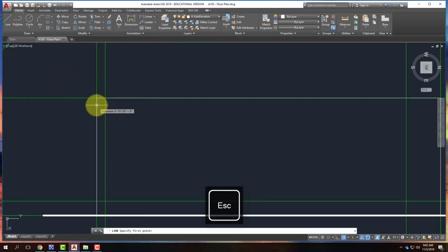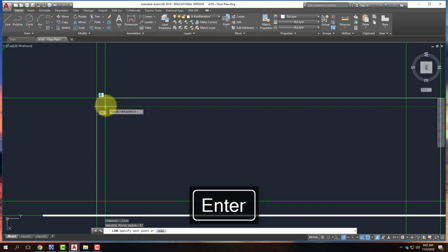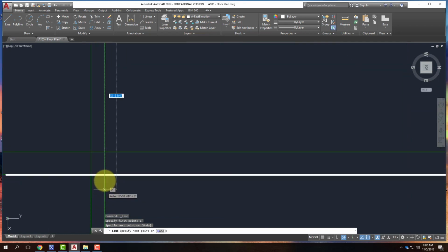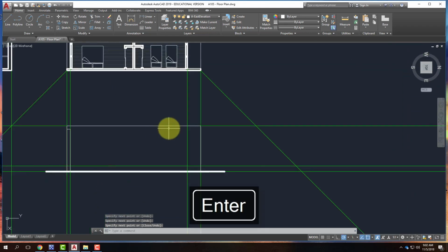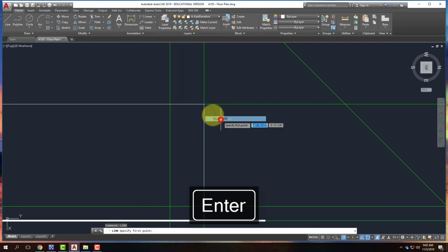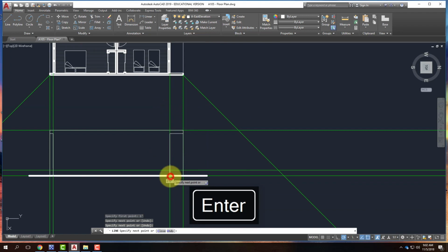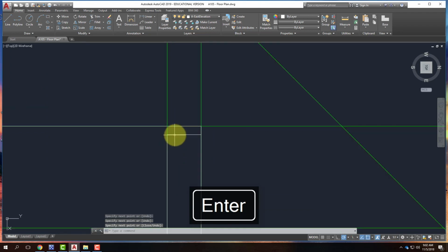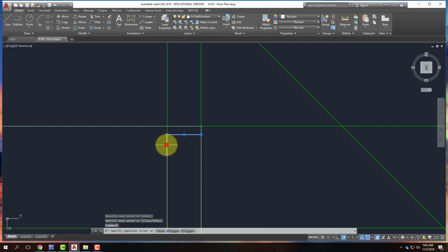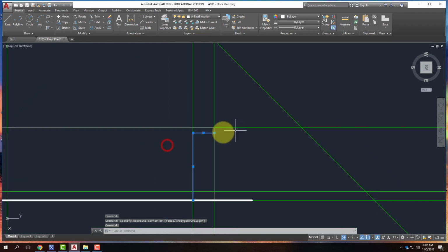Now I could go in. I could come down a foot, over and down. That represents the face of that building in the inside. Likewise here, I could come down a foot, come over, and all the way down to right there. Now, since those two are hidden, they're not seen, I should change the line type to hidden. So I'll select each of those,